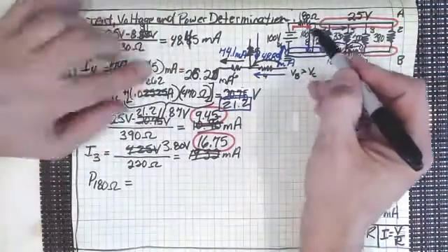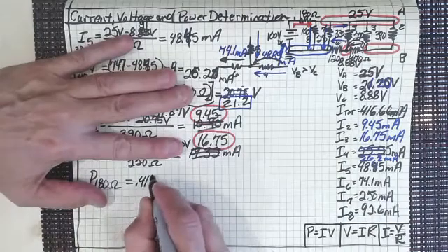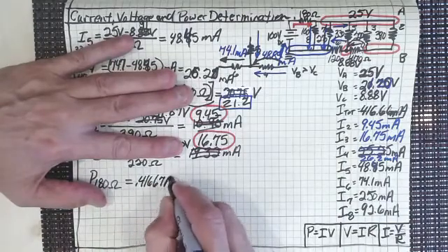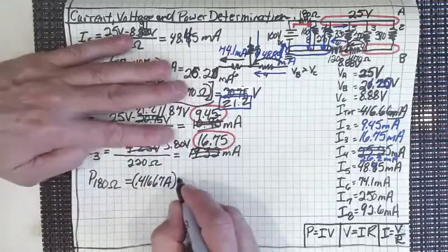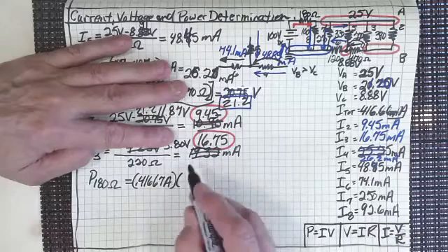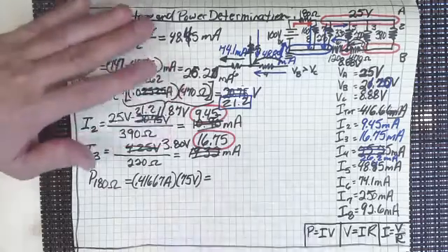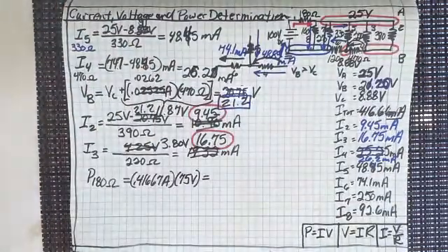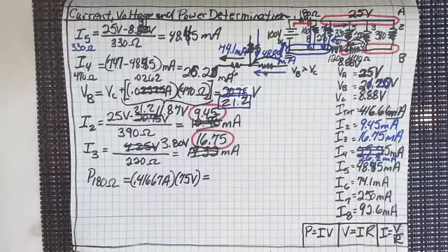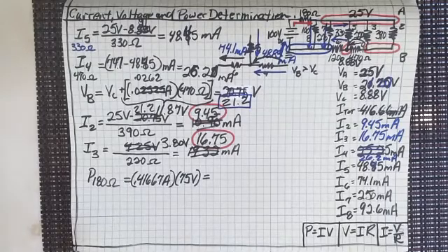If we look at the amount of current, that's the maximum current going through there, 0.41667 amps flowing through. And we know the voltage across that is going to be 75 volts, the largest voltage differential in our entire circuit. The real question is, is that going to be more than 1/4 watt? Volts times amps equals watts, that's right.